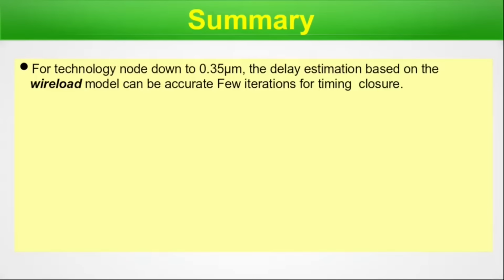Summary. Here we are summarizing all the points we have discussed so far. For technology nodes down to 0.35 micrometer, the delay estimation is based on wire load model, which can be accurate with few iterations for timing closure.